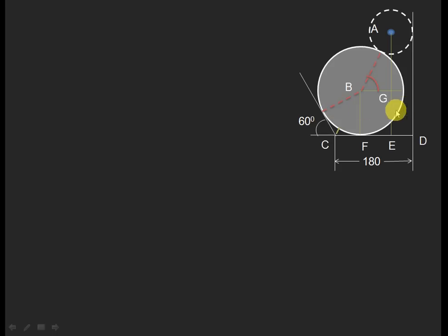Here this is the second sphere free body diagram, on which certain reaction forces will be acting. One is already equal to R2, and another reaction force will be applied by the inclined wall, that is the channel wall, acting perpendicular to it, and another reaction force will be acting at this contact point here. Before that, I have represented the weight of the sphere as 500 newtons, which is given in the problem. Wherever the contact is taking place, a reaction force will be acting. So now we try to draw the line diagram. This R2, we already got it as 240.8.